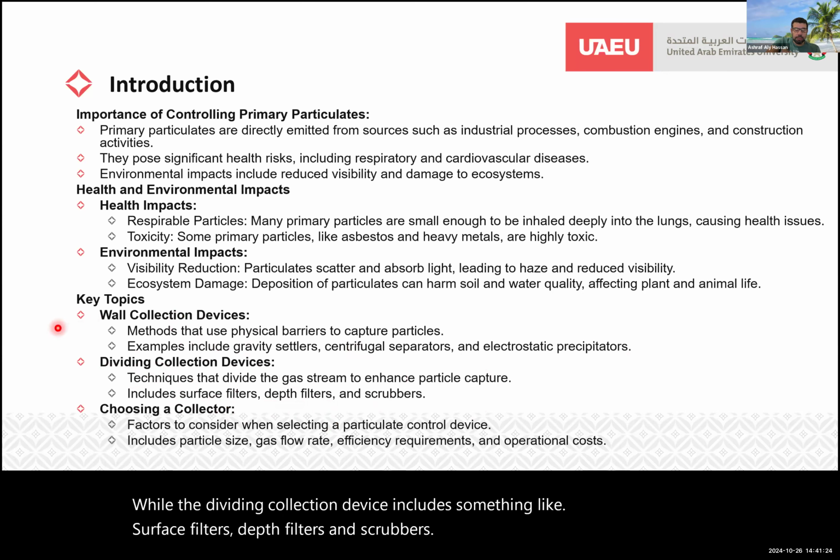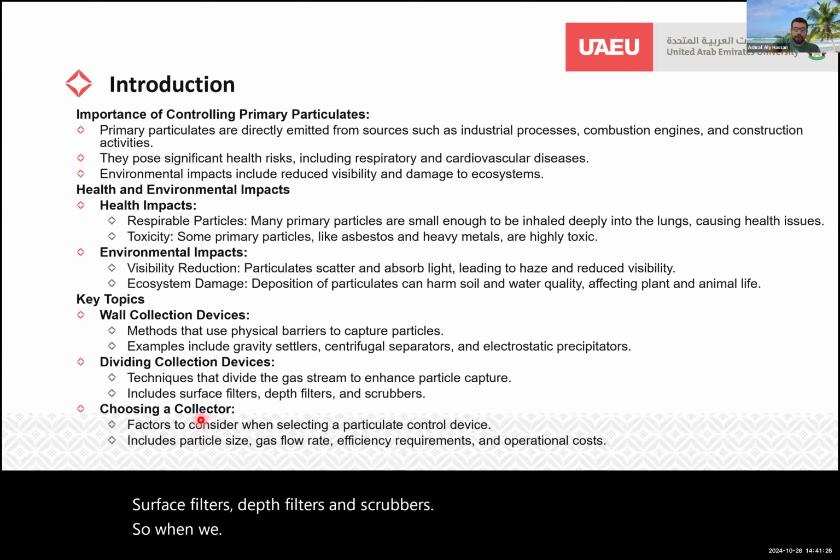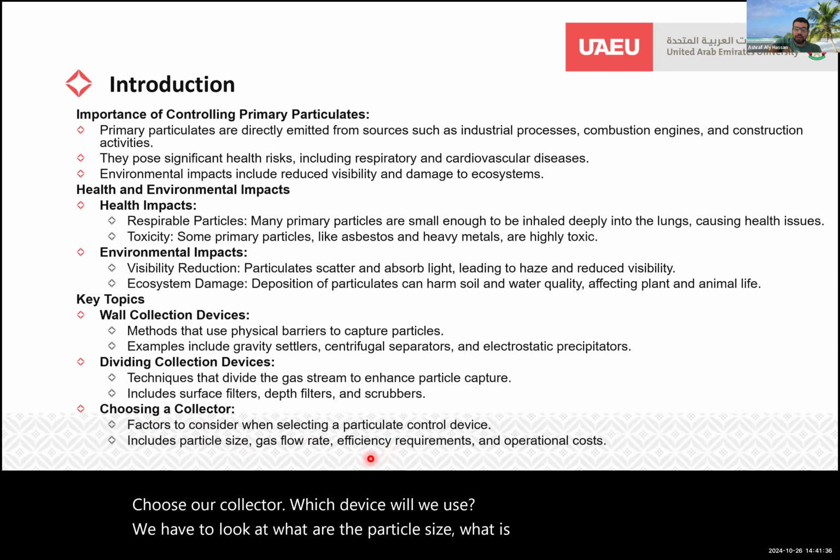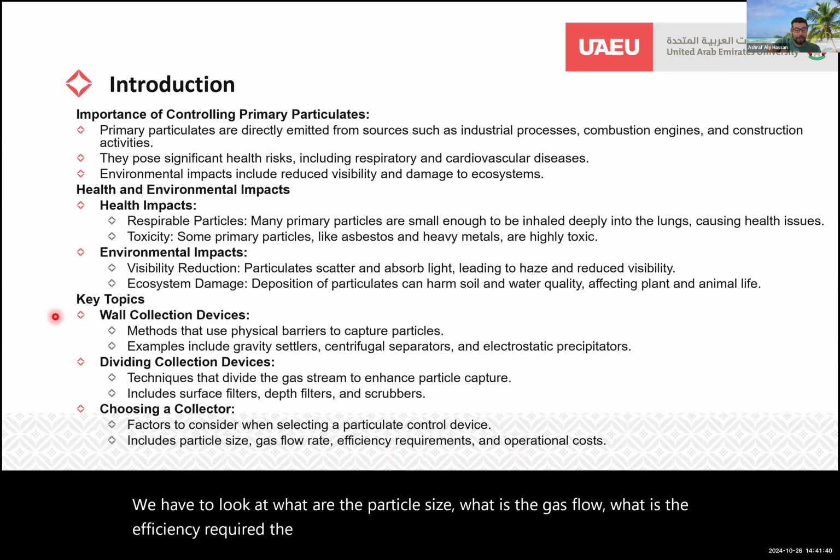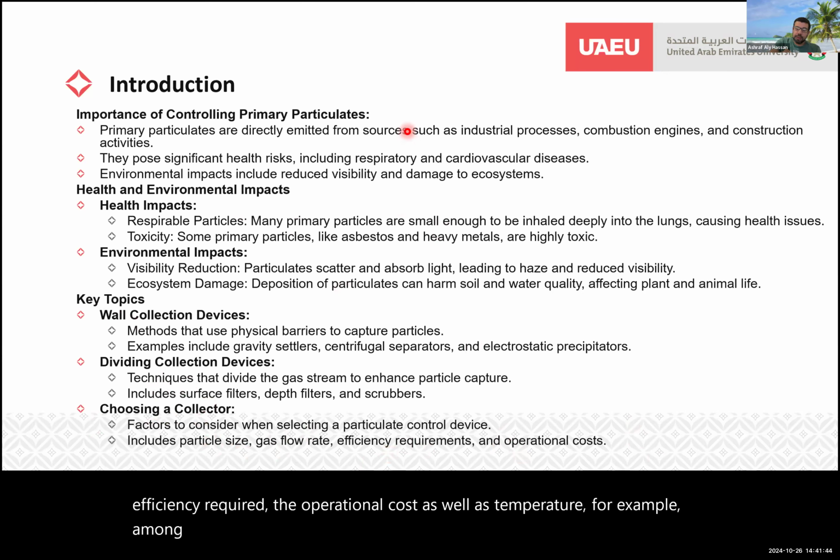So when we choose our collector, which device will we use? We have to look at what are the particle size, what is the gas flow, what is the efficiency required, the operational cost, as well as temperature, for example, among others.